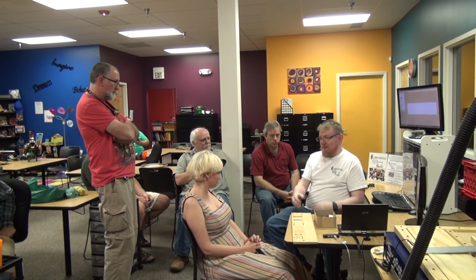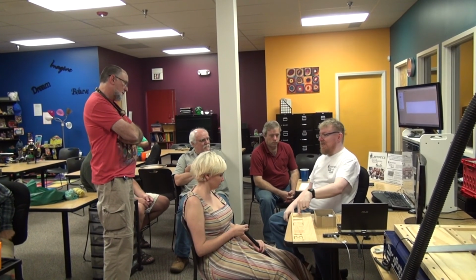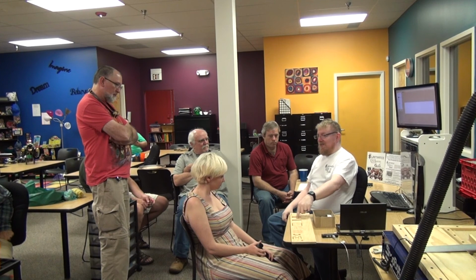And what do I mean by CAM? CAM is computer-aided manufacturing. If I just draw a square in software, the computer and the CNC machine don't know what to do with that square. Does the operator mean I'm going to cut out around the outside of it? Does he mean I'm going to cut out inside the line? Does he mean I'm going to cut on the line? What size bit am I going to use? Because if I gave this same rectangle but put a bigger bit in, I'd get a totally different physical product when I'm done, right?